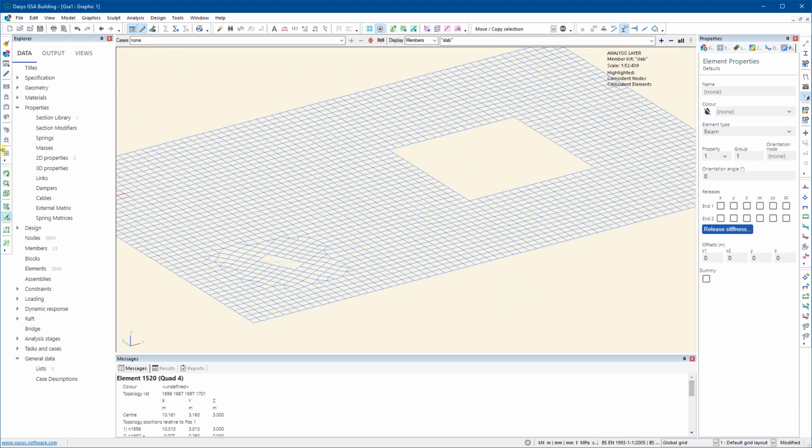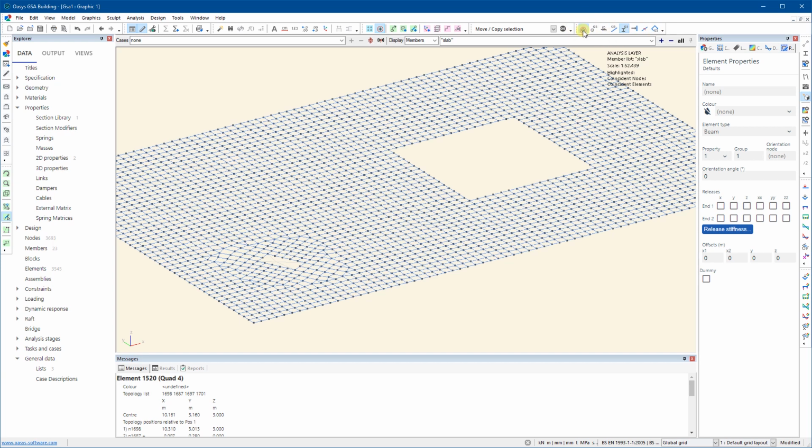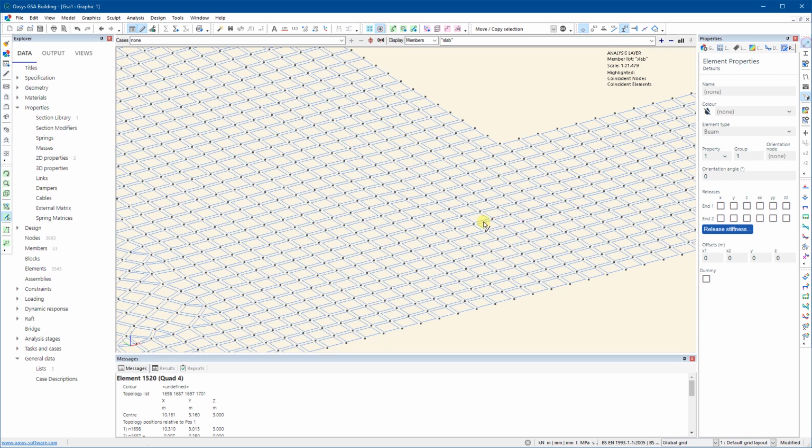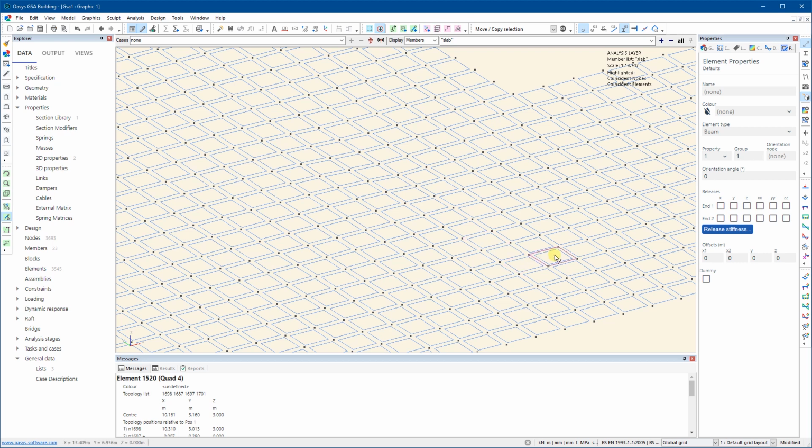The other thing is if I put on the nodes, so you've got the annotation tools up here, you've got your nodes, you can put on the nodes that are on the elements. If I shrink them so I can see this. So these are all linear elements, obviously. So as the name suggests there, quad 4, so 4 noded elements. Ideally, I wouldn't use those. I would use 8 noded elements.